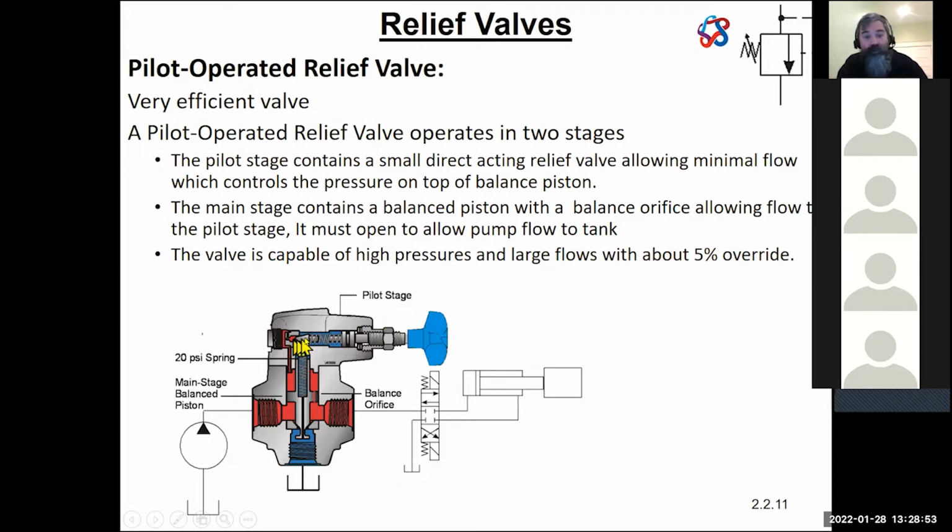This is where my super strong spring is that has to accommodate several thousand psi, or the force of several thousand pounds against it. It's only going to accommodate really the pressure, and a small bit of flow is going to go through there. Its purpose is to cause the main part of the valve to open and close, letting the main volume of the fluid go through.